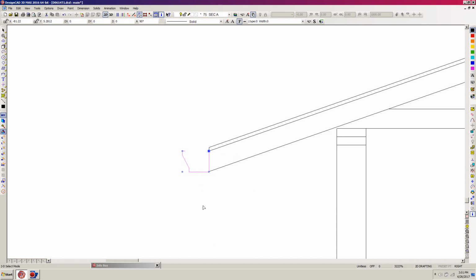Well, that's kind of big though. So what I'm going to do is I'm going to explode that symbol, and I'm going to select all of these points and go to orthogonal mode. Drag this one point, which will drag the rest of the highlighted points with it. Just right click to it and move it in a little bit, and then left click. There, that looks better. And hit escape to unselect.